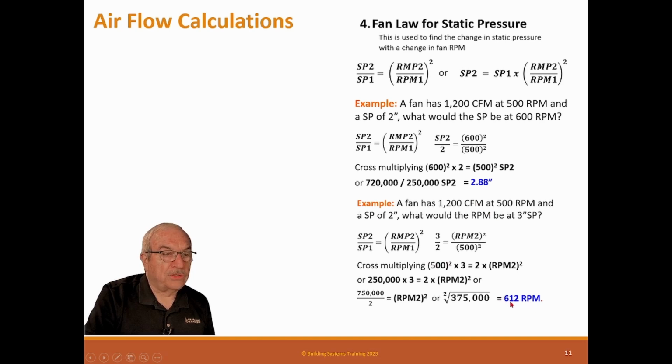Now you'll notice that small changes in RPM make bigger changes in static pressure as a percentage. So you have to be careful when you make changes that you don't get too high. Now remember, a lot of times in the field, you'll be doing more than one of these equations on the same thing. So if you needed to know what the static pressure was and the RPM was, now you may have to go back and do that brake horsepower one to make sure you're not over the horsepower of your motor. So these equations, of course, are very, very helpful.